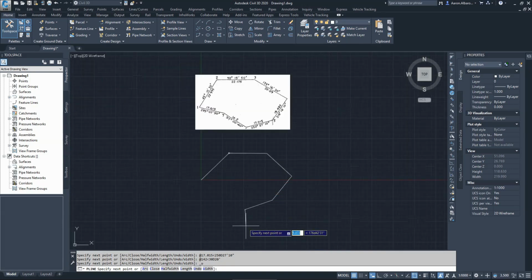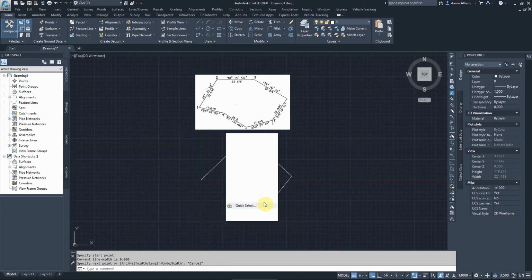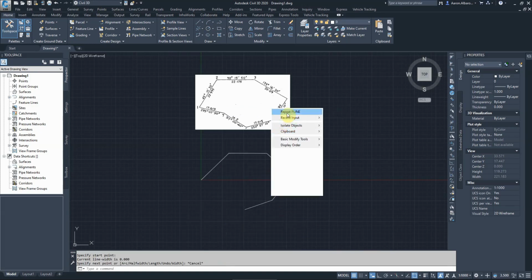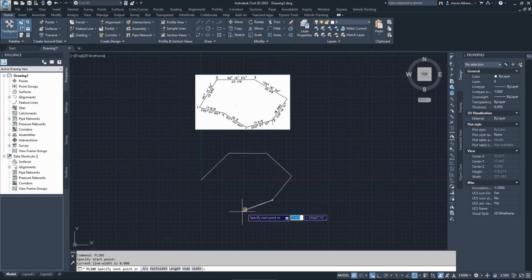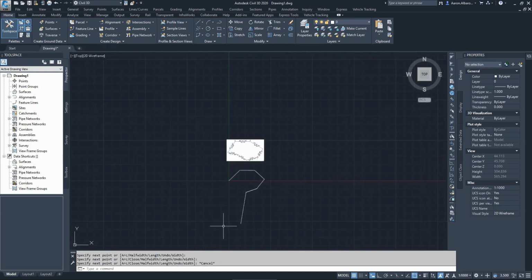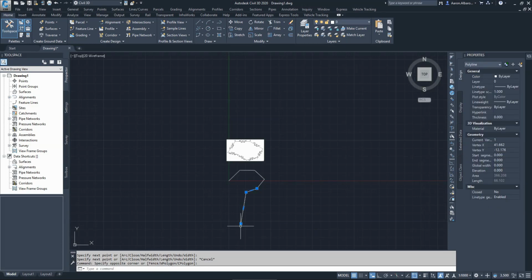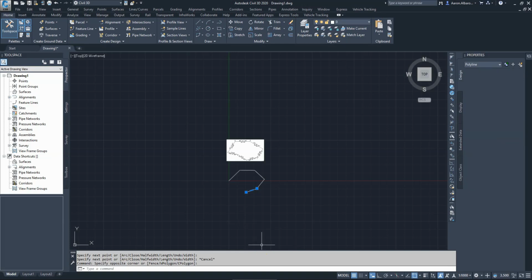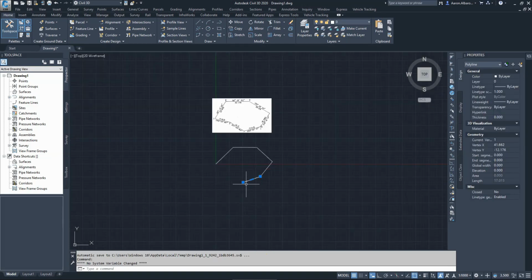And for any reason that you clicked out of this, or you drew something completely wrong, and you clicked out, you can select that and go to the last point, hover over it. For some reason my computer is slowing down, and you can say remove vertex. That will remove the last point. Just hover over it. Okay?